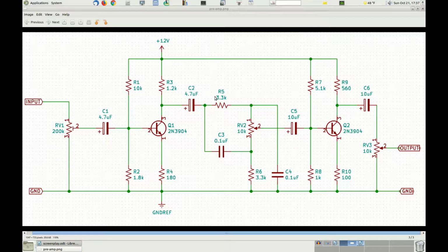Resistor R5, along with capacitor C4, provides a low-pass filter, while the capacitor C3 and the resistor R6 provide a high-pass filter. Potentiometer RV2 picks the signal more from the low-pass filter or from the high-pass filter, depending on where its cursor is positioned. Since the signal handled in here is always sinusoidal, this control does not really change the harmonic contents of the signal, like it would be done by a hi-fi preamp.